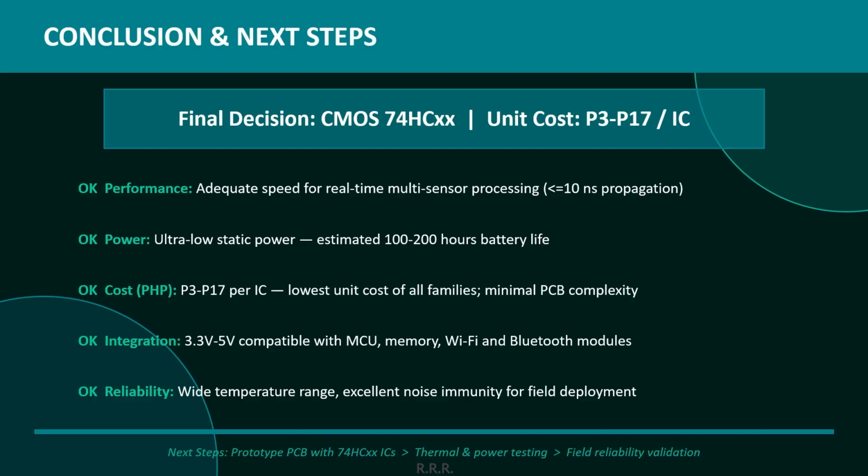Cost. At 3 to 17 pesos per IC, CMOS is the most affordable family by a significant margin. For a mass-produced consumer device, this directly improves our competitiveness in the Philippine market. Integration. The 74HCXX series is fully compatible at 3.3 to 5 volts, matching the operating range of every microcontroller, memory module, and wireless SoC in our current design.